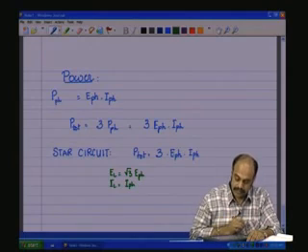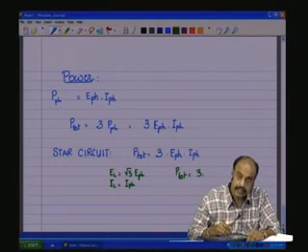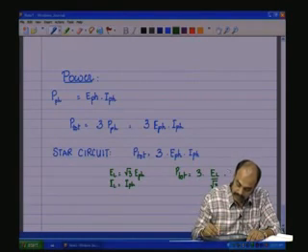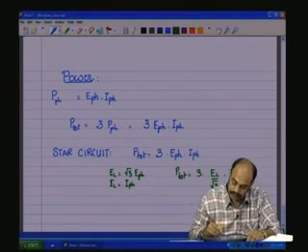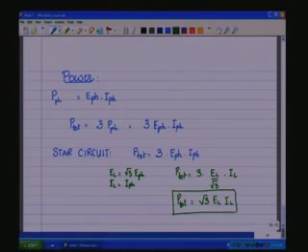So, substituting these here, you have P total is equal to 3 into E phase, which is E L by root 3, I phase is same as I L, and therefore, we put it as I L. So, which is root 3 E L I L, that is the total 3 phase power. Root 3 line to line voltage into line current.